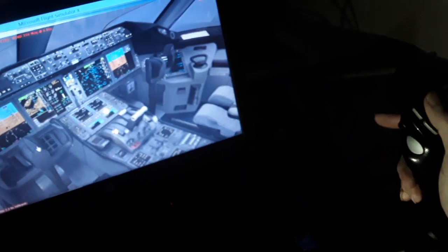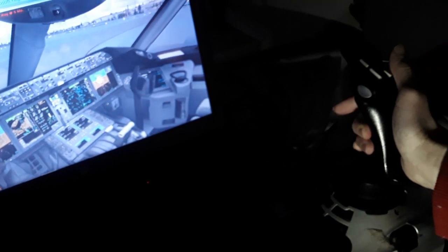And as in the Airbus, you can make climbs and descents. When you have a fly-by-wire aircraft, you have the flight control computers. Same as in the Airbus, you make left and right turns at 2.8 G, the acceleration of gravity, or 67 degrees of side stick deflection, left and right. It's limited in the Airbus aircraft: 2.8 Gs in left and right turns, or 67 degrees maximum side stick deflection.